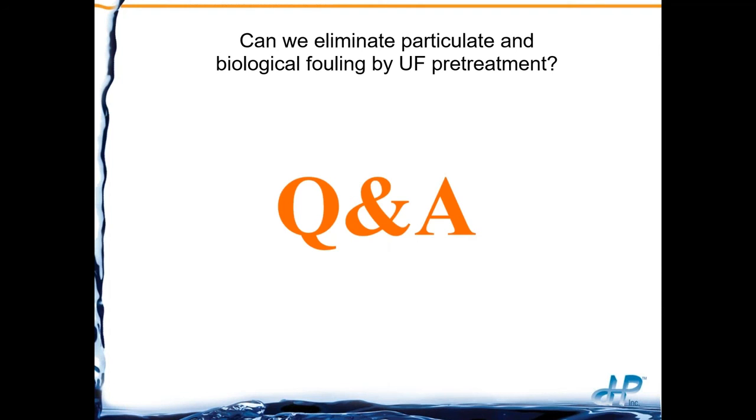So an ultrafilter is not an end-all be-all to stop fouling of an RO system. Yes, it'll get the feedwater particles filtered out as long as there's no damage to the ultrafilter, but it will not stop the biological fouling of an RO necessarily.